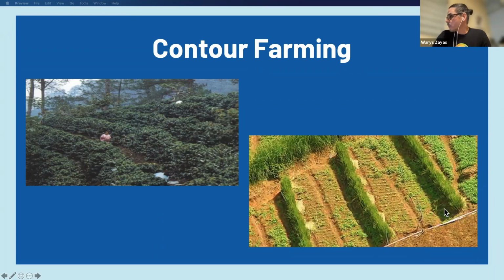This is another common technique. And in this picture, you can see some ditch systems, hillside ditches to discharge water. As well, here we have another good practice: those barriers are made from a grass named vetiver, and vetiver grows almost anywhere.